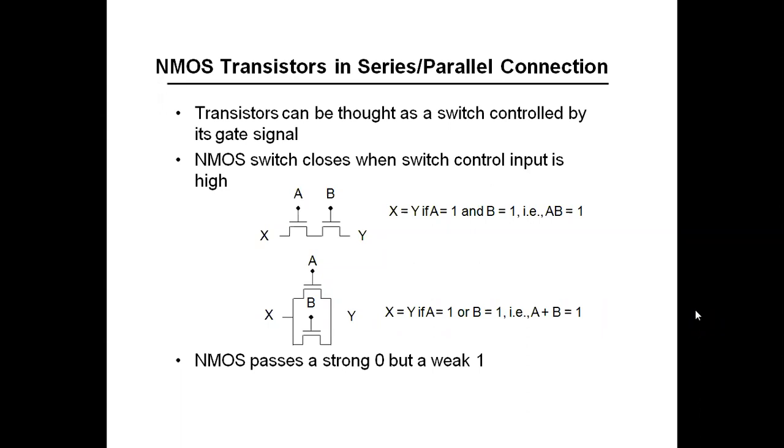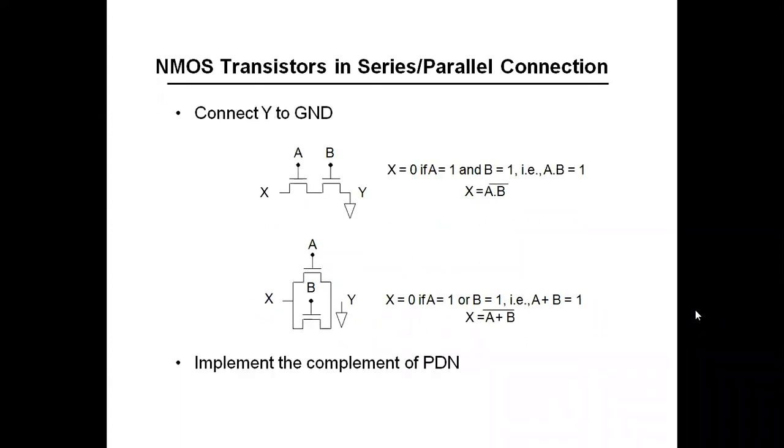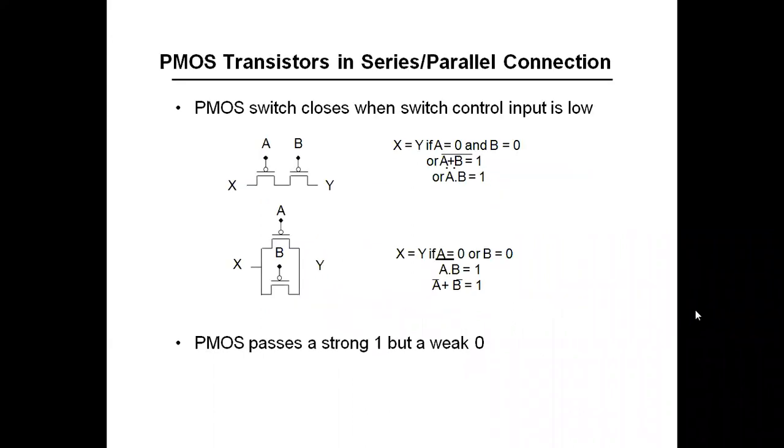The series connection is an AND operation and the parallel connection is an OR operation. The same is the case with PMOS: series is AND, parallel is OR.